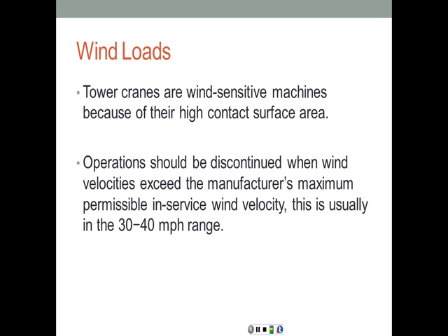So if you have strong gusts of wind, you may suspend operations until that gust is over and then resume work later on. If there's going to be a storm, then the crane must be locked and secured so that the boom does not rotate, as we have seen in the previous video clip.